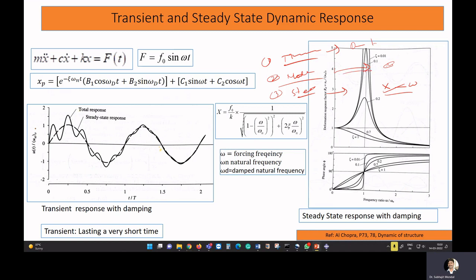And in the modal analysis, we observed that we can only find frequencies and mode shapes. Here also you can observe that in the modal analysis, we do not have any information about damping, because the equation we are solving for modal analysis does not include any damping. So we are getting real eigen solutions: real frequencies and real mode shapes.